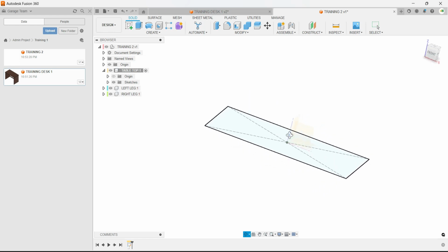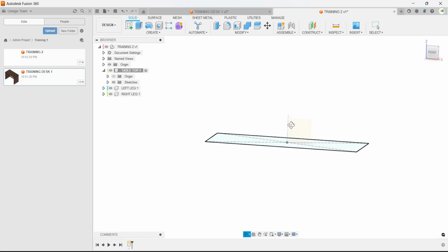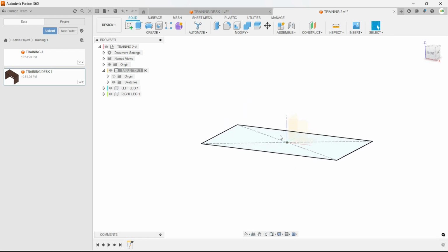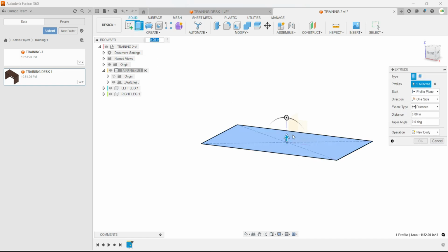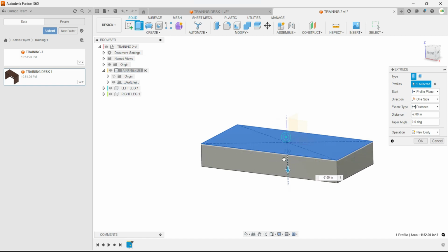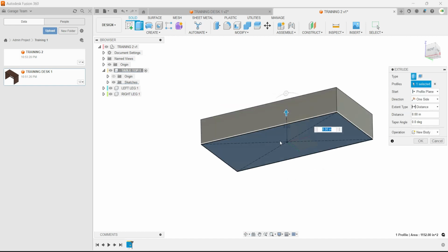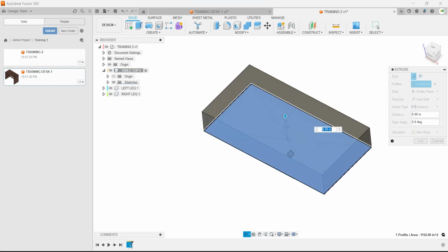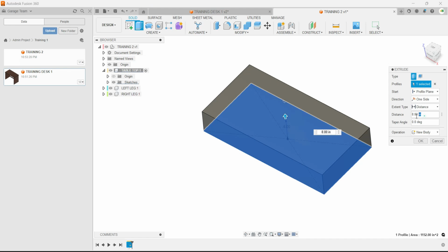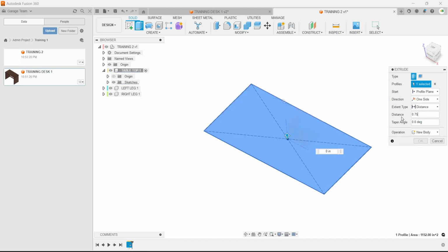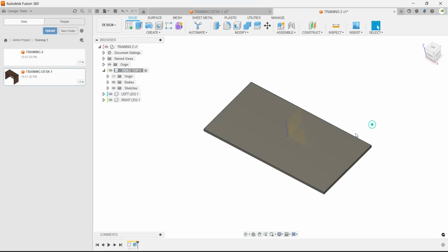And now if we hold the shift and the middle button, we can rotate again. And we're going to give some geometry to our sketch, add some volume. We're going to click extrude, and we have a choice to extrude down or extrude up. Now, since our legs are going to go down, we want to take advantage of this YX plane, which is right here. So we're going to extrude up. And we're just going to extrude the width of a plywood thickness. So we're going to do 0.75.